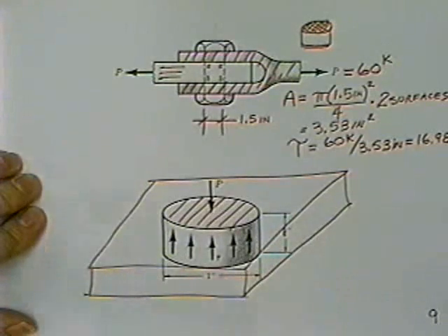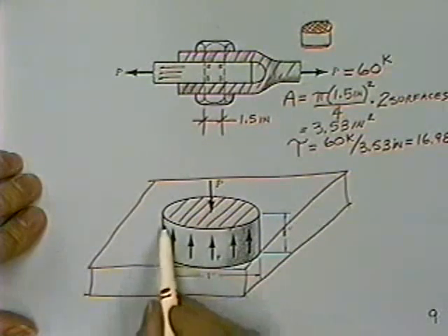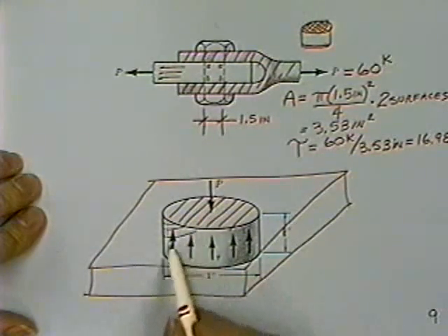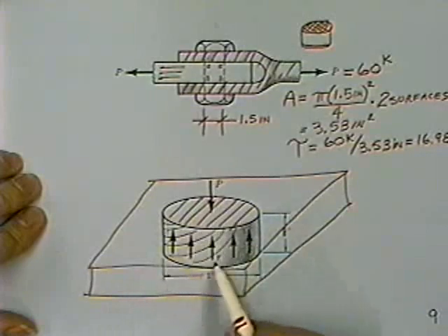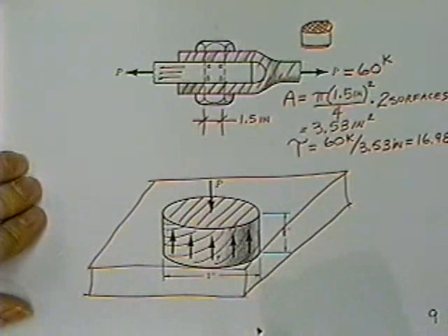And the question is, what stresses are induced in this little plug of steel? Well, in that case, although you still have a pi d squared over 4 area showing, that's not the area that's holding the structure together. When he tries to push the plug out of the plate, this is the area involved, the area around the piece of steel, even though it is still a shearing stress working to resist that.